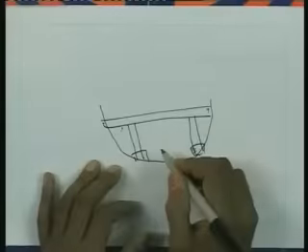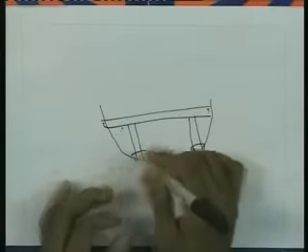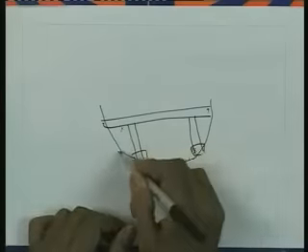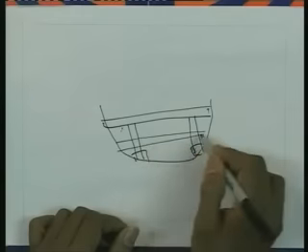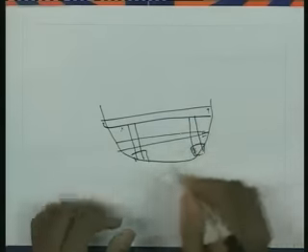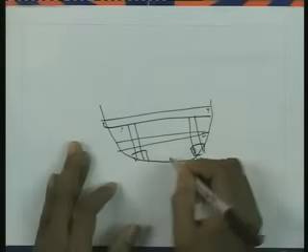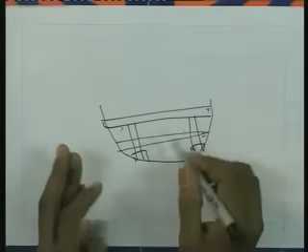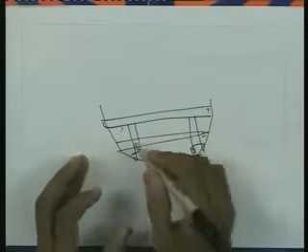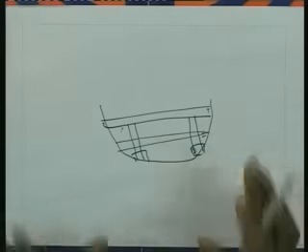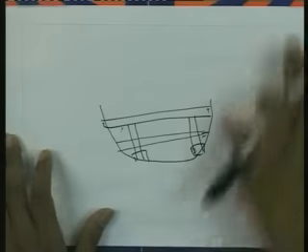For the bridge, depending upon the monsoon or rainfall throughout the year, we see how the water level varies, whether it increases or decreases, what the flow velocities are at the particular location, and whether there are any erosion problems on the river bank. All these things we analyze physically. So this is the so-called physical analysis.